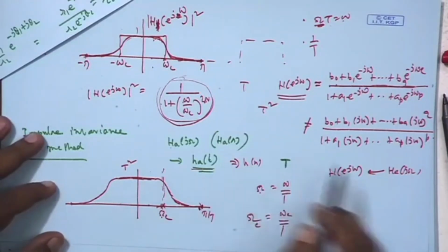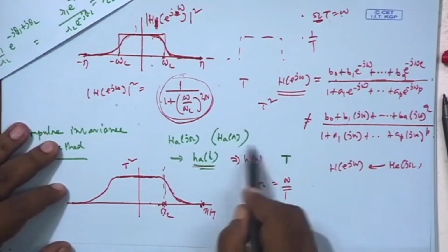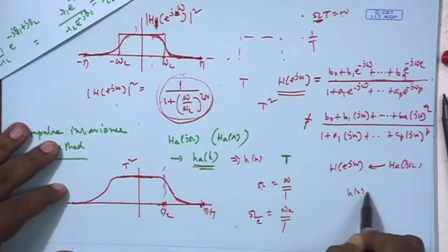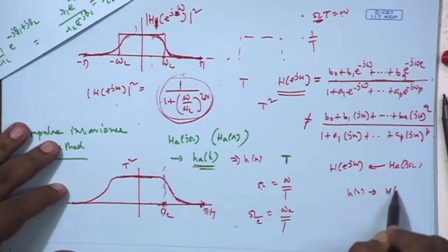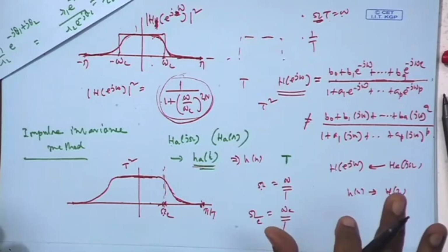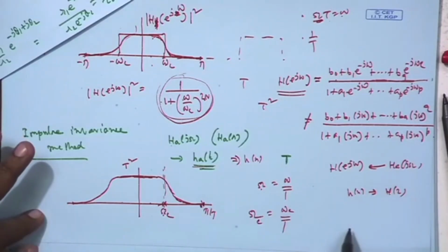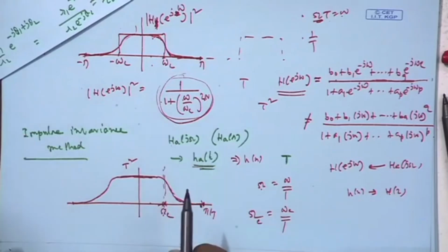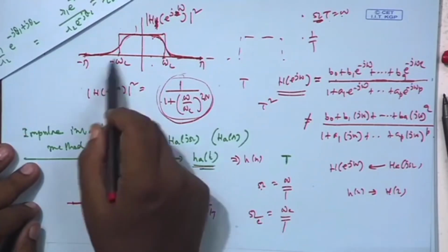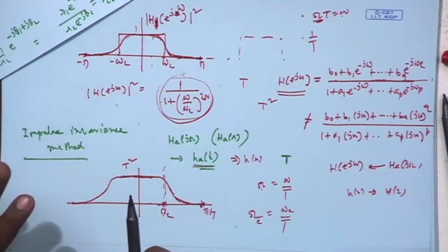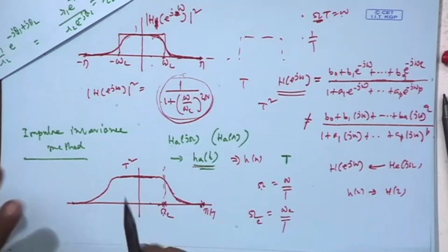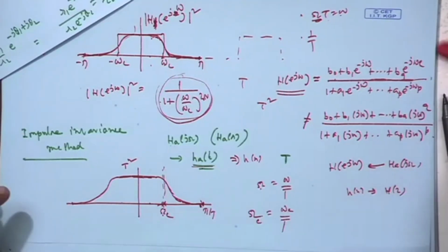Then you take the Z transform of this H[n], and that gives rise to your filter, whose frequency response will be similar to the analog frequency response, and therefore the magnitude response square will be the same as the original magnitude response square. I repeat again.